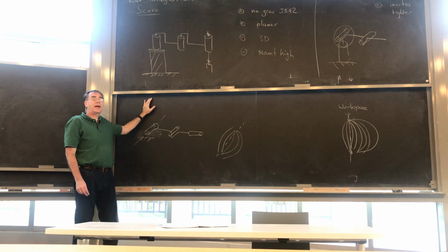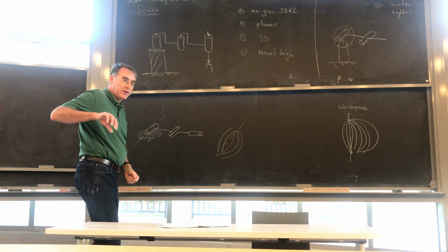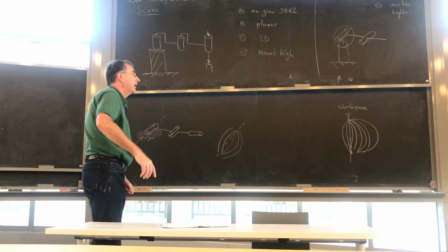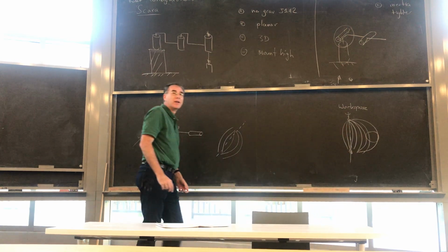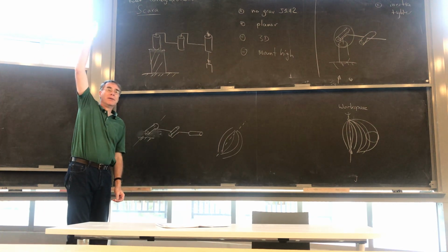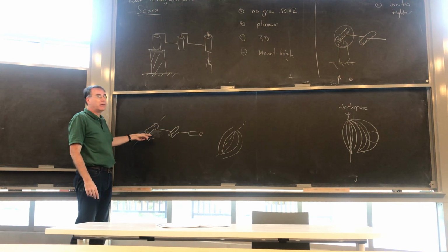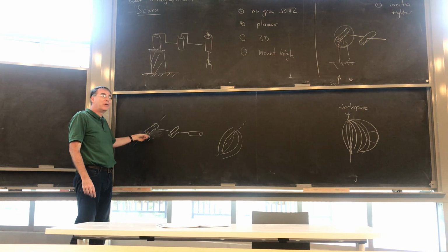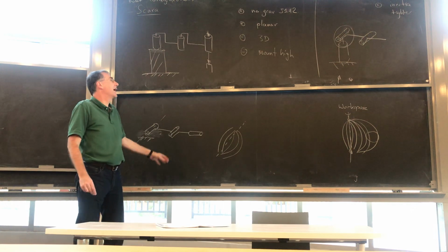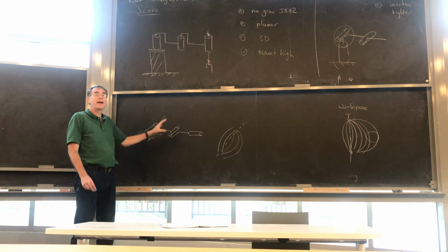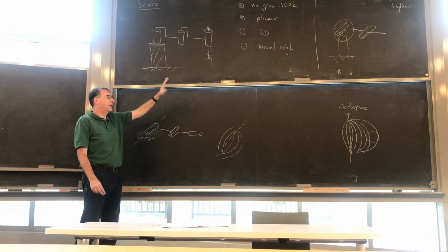So part of this is, well, where's your workspace? And a lot of times when we build a robot, you're going to reach over and grab something. Well, in that case, your workspace is probably right out here, in which case that's totally fine. If you really want to reach straight up, you probably want this kind of a style. And if you think about it, if you reach straight up, the gravity loading is actually not that big a deal, right? The gravity loading is only a big deal if you reach out. So I feel like I'm spending too much time. I don't really want to go through it, but there are all these trade-offs that you can potentially make. And I know that we talked a fair amount about SCARA and everything, so I just wanted to lay that out a little bit.